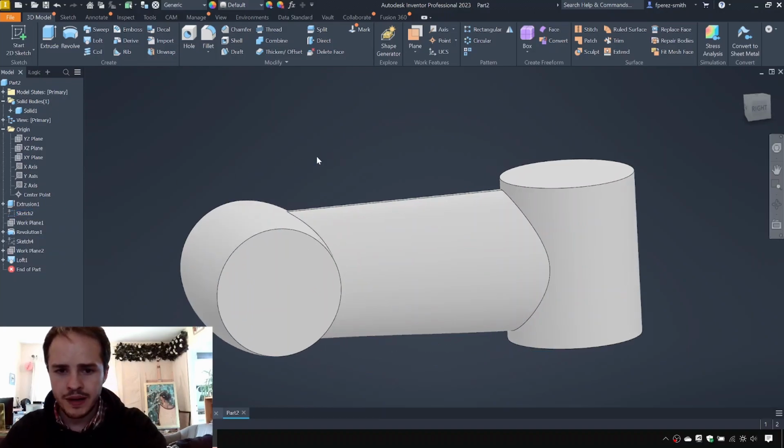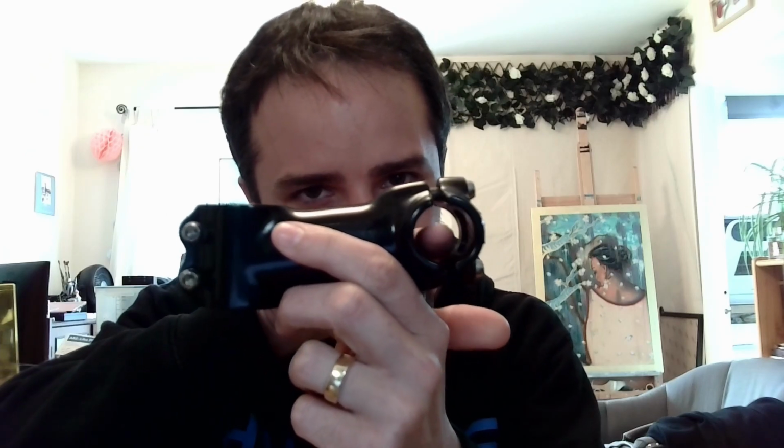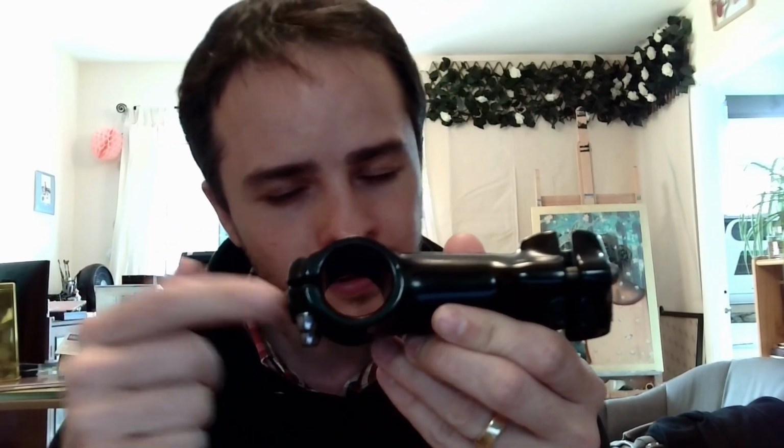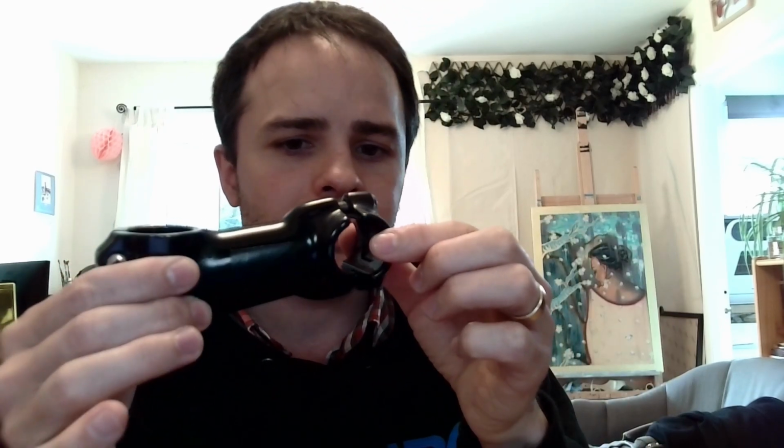Lovely. Okay, so what do we have so far? We've got a shaft, a cylinder representing that shaft, a barrel representing this shaft, and we've got a lofted body here. Next, what we're going to do is add in these humps here. These humps are going to hold the bolts, which are going to hold this part that separates. We're going to take a slightly different approach when we come to the rear barrel, the rear shaft here. But yeah, we're going to make these, I guess you could say, shafts that hold the bolt holes. So let's get to it.